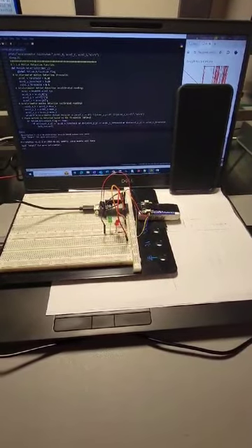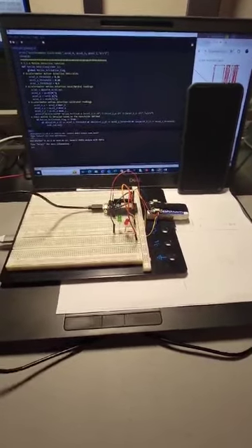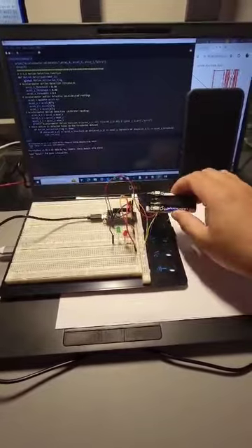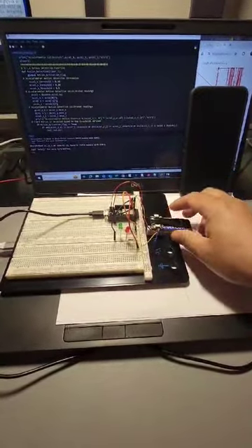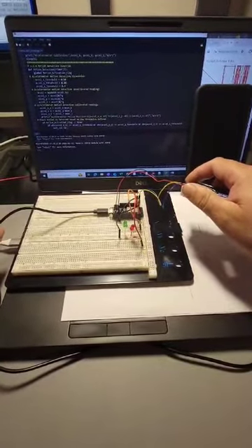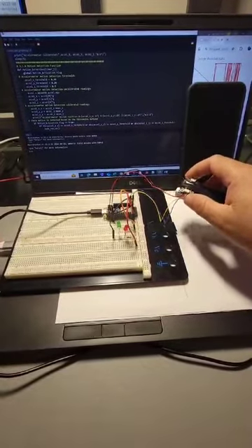The ESP32 board is connected to the COM6 port in the computer using a USB cable, and that powers the board. The MPU-6050 sensor consists of a gyro, accelerometer, and temperature monitor, and it is connected to the ESP32 board using these 4 cables. I'm using a 4-pin cable that I'm going to describe below.